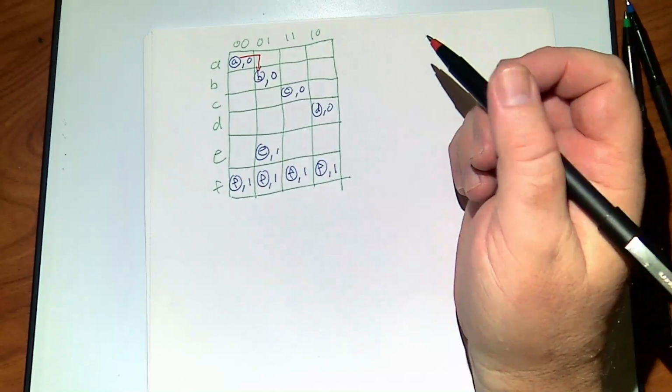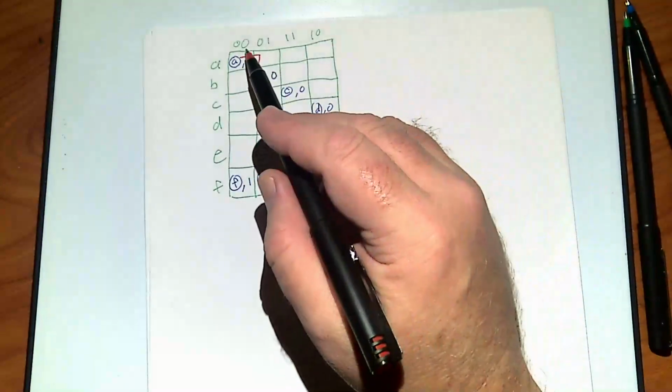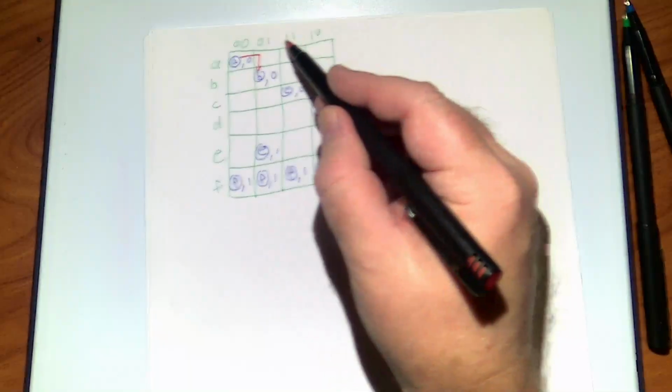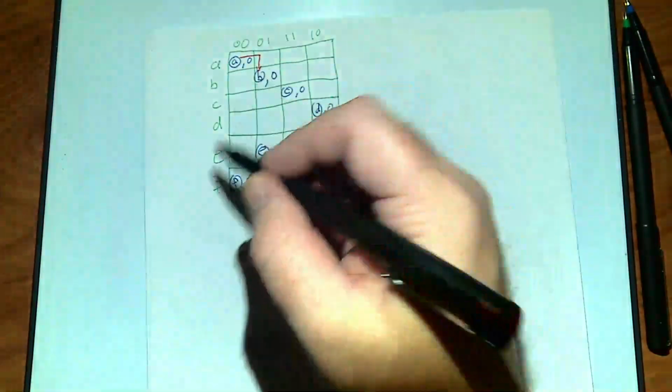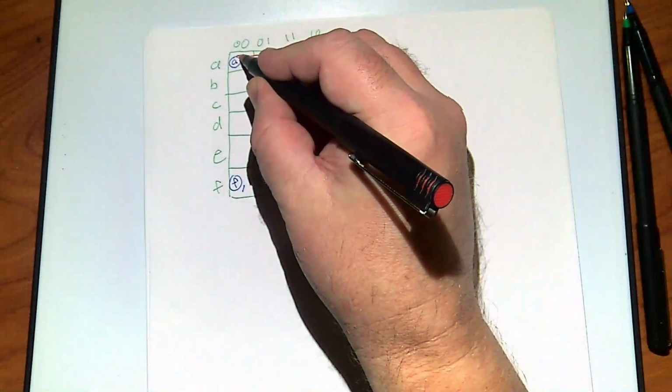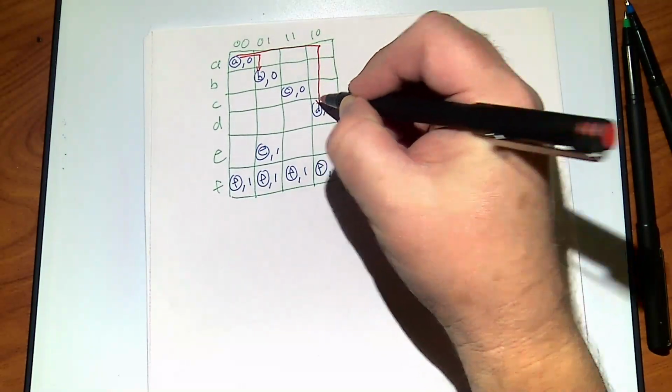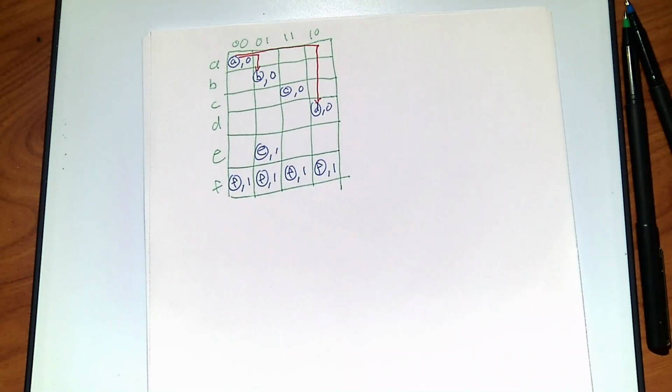In most of these cases, I'm only going to worry about the transitions that don't involve races. So I'm not going to worry about going from 0, 0 to 1, 1. A is in the 0, 0. So the only two I'm going to worry about are these two. And let's say it goes to D. Fair?